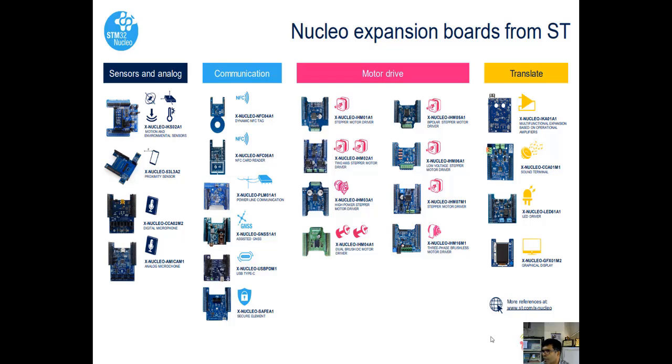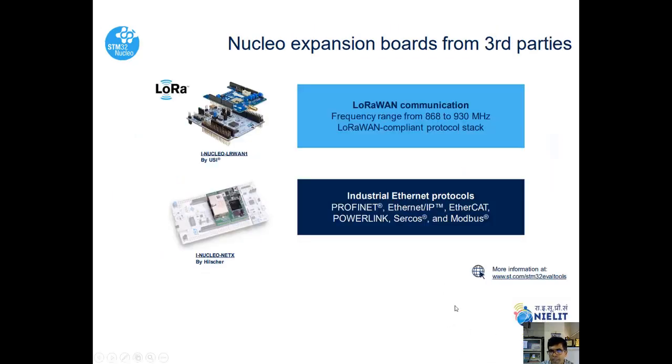So all these kinds of motor drives are available as shields. And similarly for translation logic, there are graphics, LED drivers, and for sound sensing modules, etc., available as expansion connectors. So you can directly piggyback those connectors on top of your Nucleo development boards, and you can start prototyping your applications.